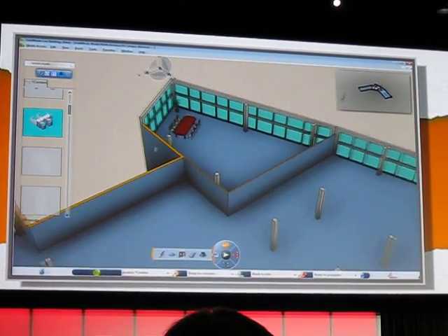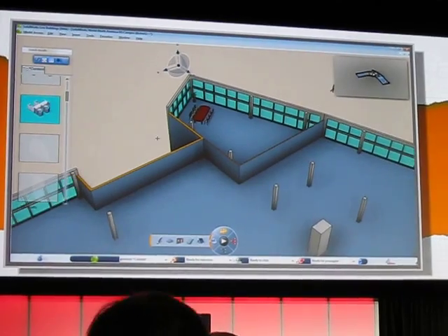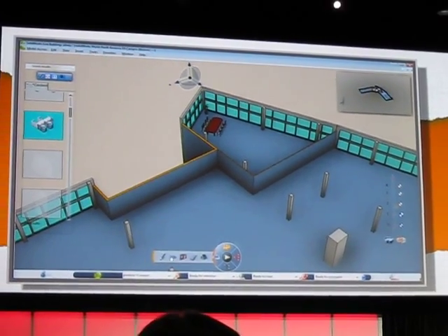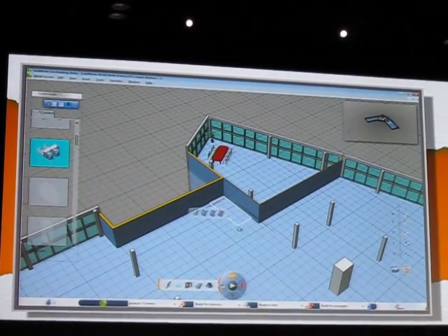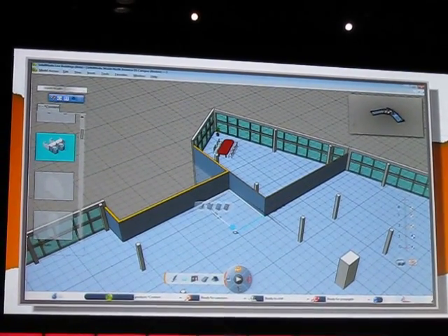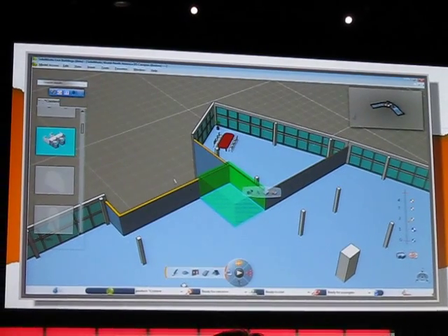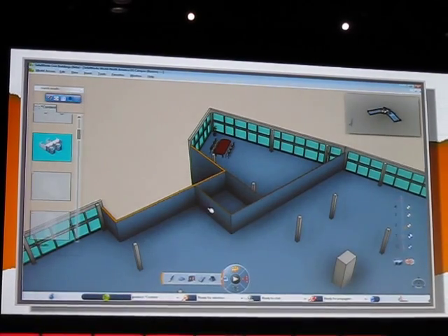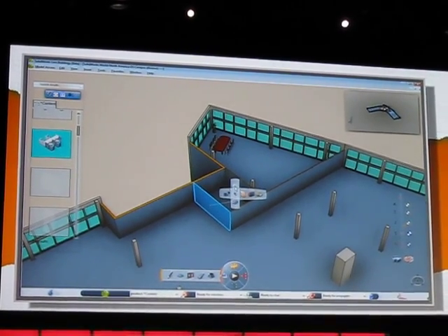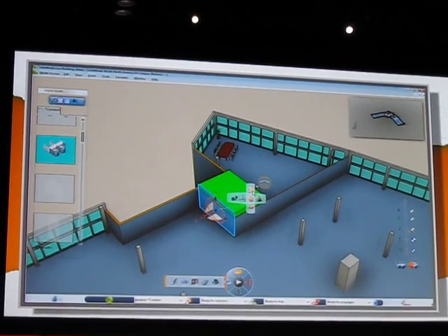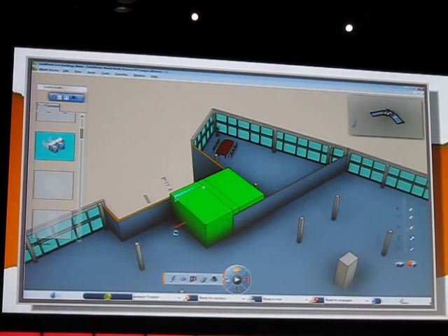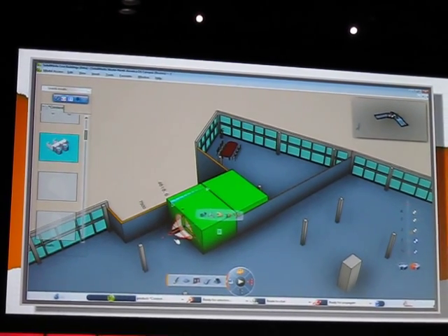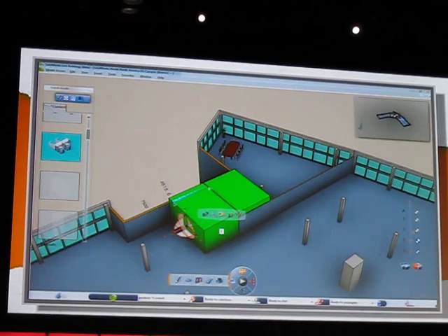Now, of course, we need to add an office for the CEO's assistant. So we'll just go ahead and drag and copy to create a new office right next to this. And as before, we can just take that and use the triad and copy and paste that over to the left. Perhaps make an office for another colleague, and then if we pattern it, perhaps I'll take one of those myself as well.